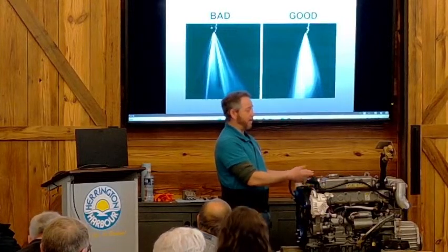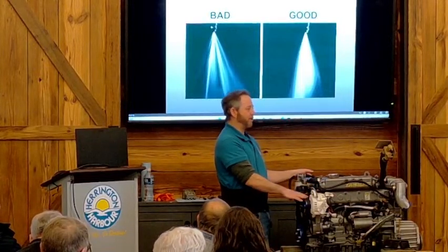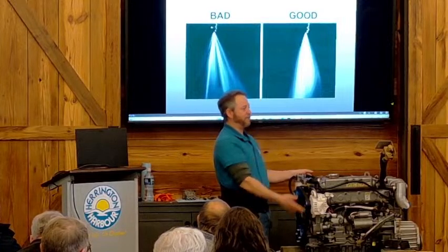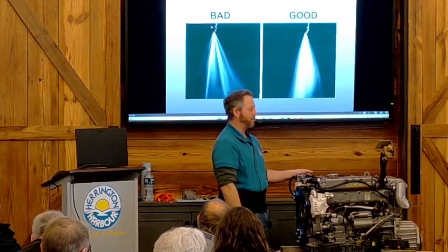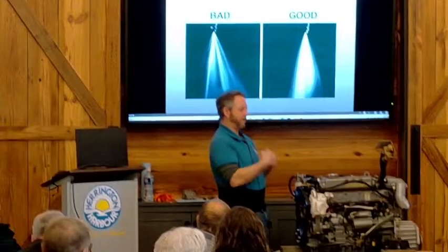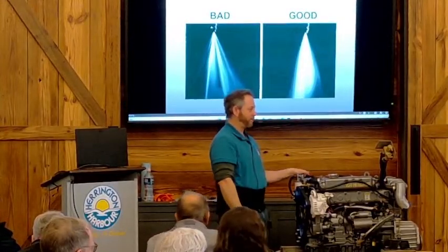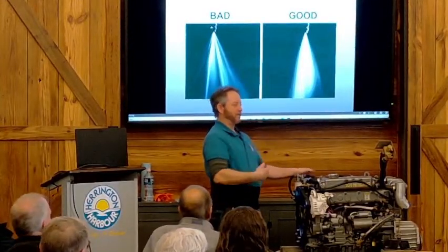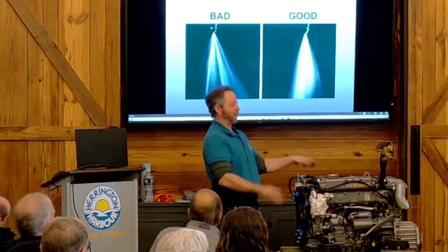But every now and again, like once a day, before you actually get to your no wake zone, run it at full throttle for 3 to 5 minutes. That way you generate extra heat and that will burn that carbon off. And it also tells you the condition of the bottom of the boat and your cooling system.